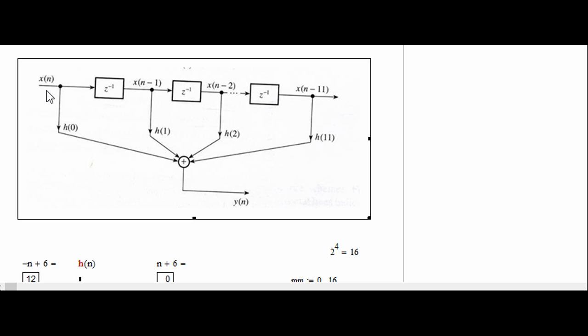Normally on expensive sound systems you'll only hear your speaker switching on after a bit, because these filters are actually switched on. If you do some sort of graphic equalizer on your PC, you can always hear it takes maybe a few seconds, but there's a definite time delay after you made your decision. After it calculated the coefficients for you and placed them in there, there's a time delay before you can actually hear the answer, because it waits for all the shift registers to fill before it starts doing the filter. So it's a real-time filter, but it's not a real-time adjustable filter.